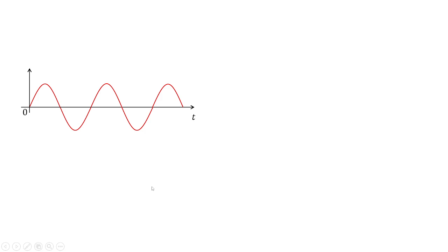Okay, so anyhow, after this, let us see what exactly the input voltage is. Input voltage is nothing but a sine wave whose value is given by V input is equal to Vm sine omega t. And how do we obtain the average value of a periodic signal? You have V average is equal to 1 by time period, integral from 0 to T, V in dt. But what exactly is V in? V in is Vm sine omega t.